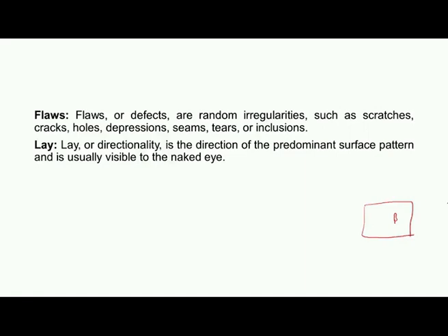Such things are known as flaws. And lay is the direction of the predominant surface pattern which is visible to the naked eye. This appears on the surface because of the tool movement on the surface. It is like a tool mark on the machined component.